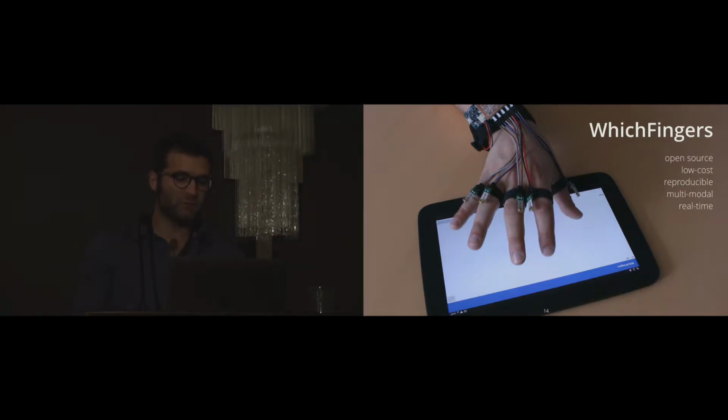We therefore propose WhichFingers, a reliable, open-source, low-cost, easily reproducible, multimodal device enabling real-time finger identification. It uses piezo-based vibration sensors, does not require calibration, works not only on touch surfaces but also on keyboards, and supports cross-device uses.